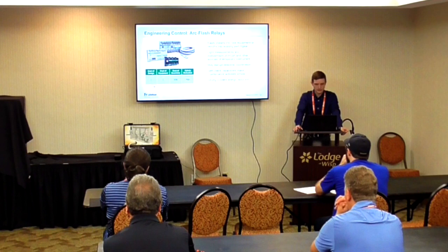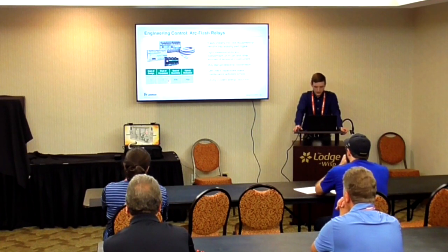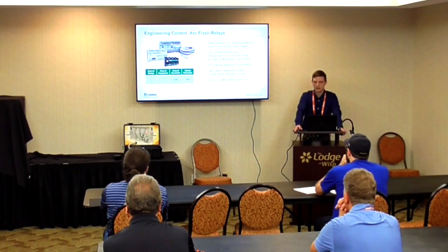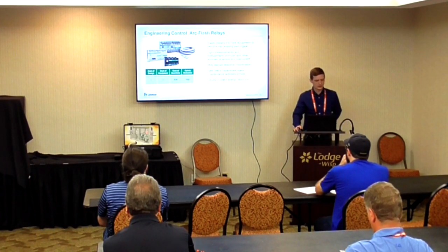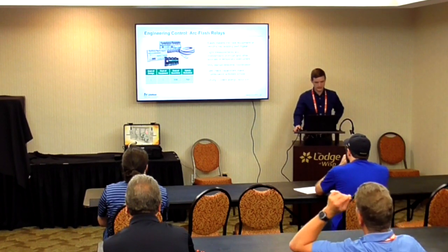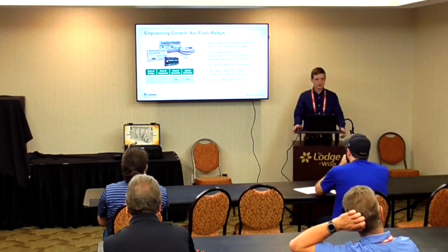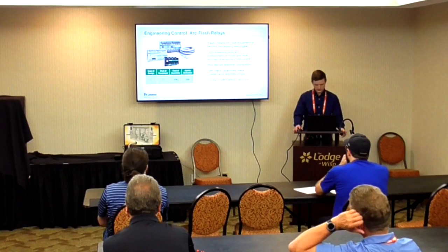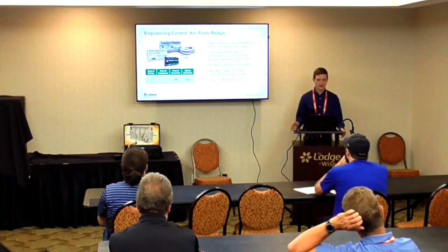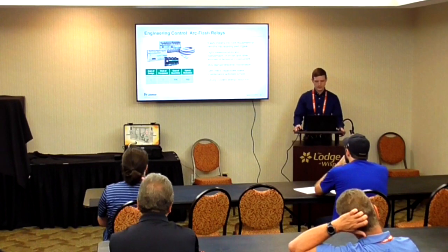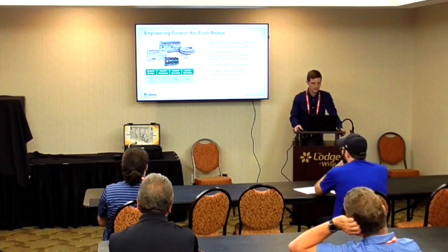So as a result, your cost of design is going to be very low. The cost of equipment is very low. Generally speaking, your arc flash relays and your sensor installation tends to be well underneath $10,000, which is much lower than some of the other ones that we've talked about. And the cost of downtime is very minimum. You're looking at typically about 4 hours to install the relay itself, along with the sensors, which means that even if you are doing de-energized work, it's very quick. And the calorie reduction is very high on this. So we looked at that linear curve earlier. We're getting that cut off well before the cable fire points, and your calorie reduction is reduced significantly.